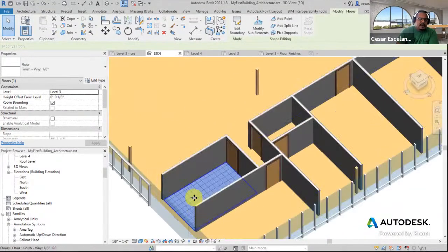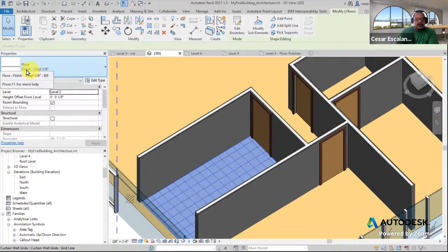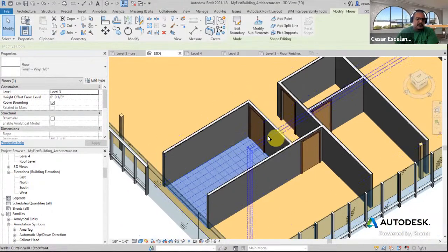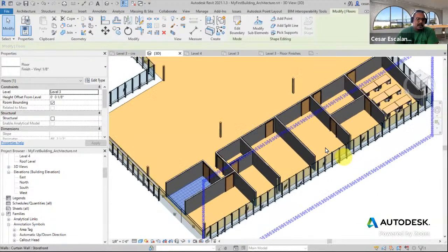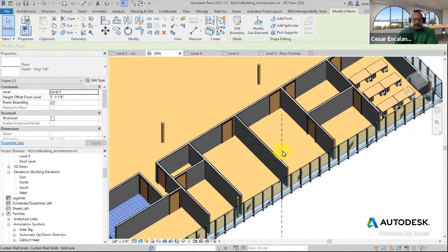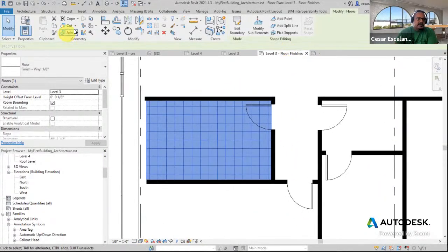And if you use this method, I would recommend to name it in a way that is clear, like they are for a user. It's a finished floor, it's not the actual slab. And make sure you put it in a work set. When we do work sharing, I'm going to show you how to do that so that they can be turned off as needed, because the contractor may not want to look at this in some views. So make sure that they are easily switched off as needed. Okay, so those are the two choices, and then you can tag this as a floor.